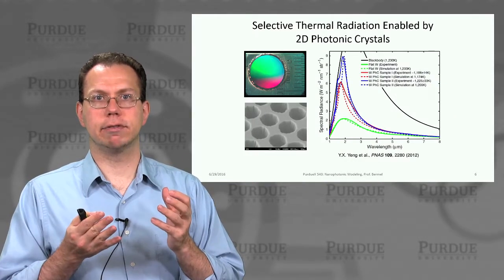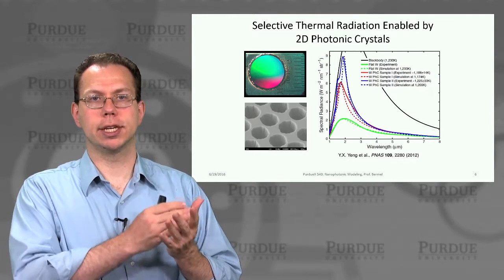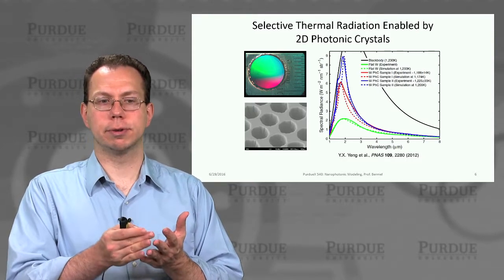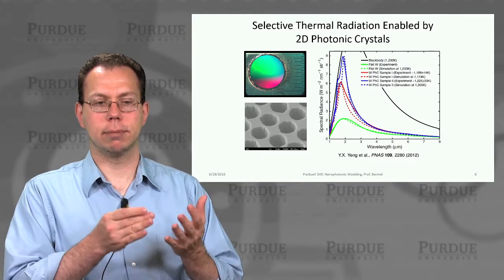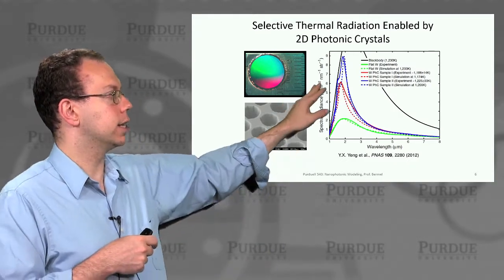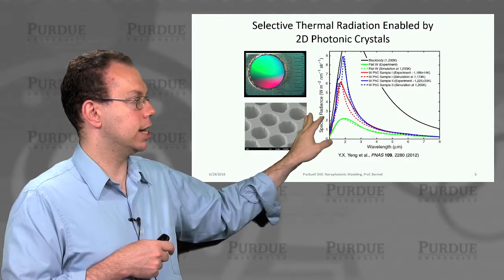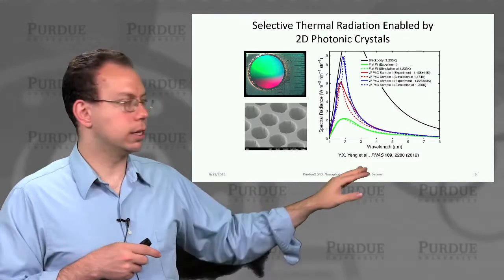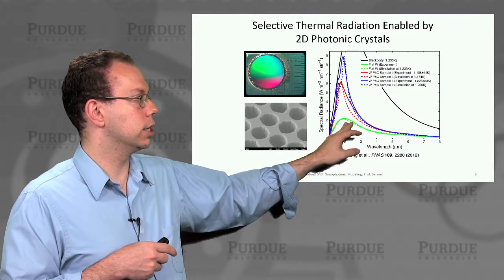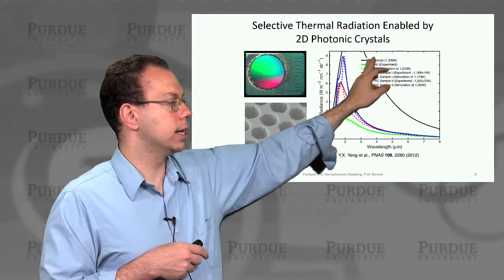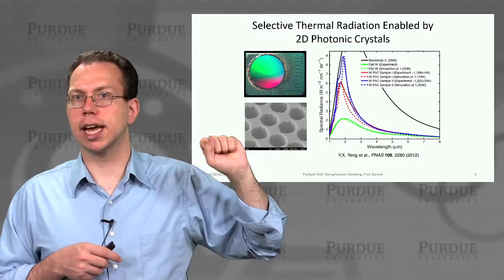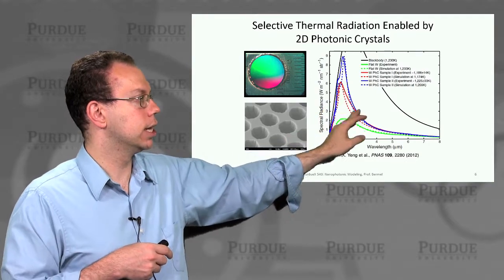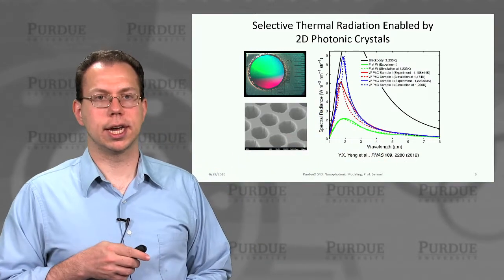And then we applied these kinds of thermal modeling capabilities, extending from our optics modeling of emissivity plus the finite element modeling of the thermal conduction, to actually compare our models to experiments. We showed indeed that many of these very sophisticated nanophotonic structures can give us thermal emission that greatly differs from either a flat piece of tungsten, which is shown here in green, or a black body shown in black, and is very favorable for certain applications like thermophotovoltaics, where we need high emissivity or spectral radiance at short wavelengths, and we need it to be low at long wavelengths in order to get high efficiencies.